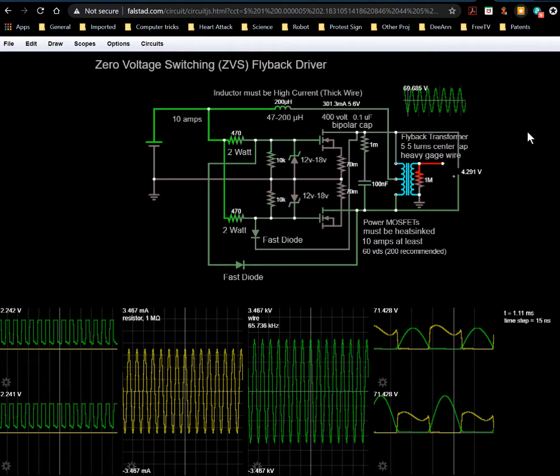But that'll quickly fall off, and as the voltage increases across it as this charges up, that current falls off dramatically. Eventually the voltage on the capacitor ends up being equal to the voltage of the battery. Okay, and then you have energy stored there, so you can actually remove the battery, and voila, you've got power stored in this capacitor until it leaks away through its leakage resistance, or until you short its terminals out on something, or otherwise use the energy in some other way.